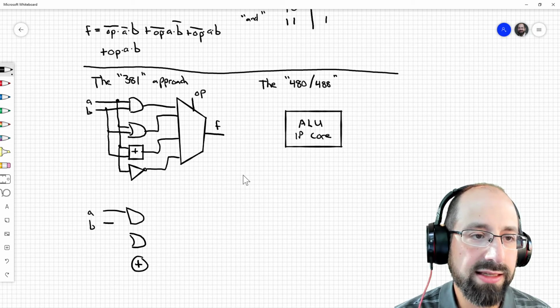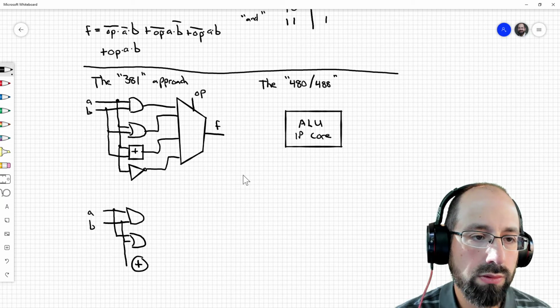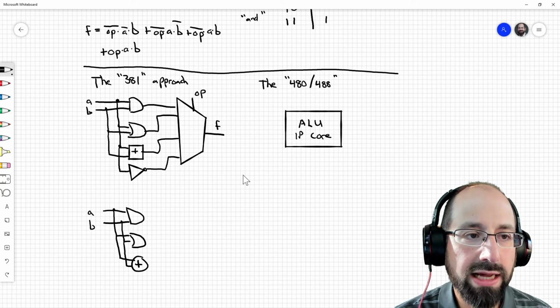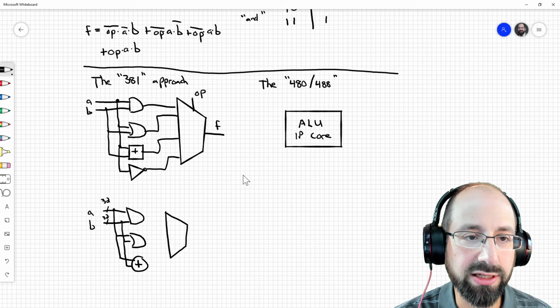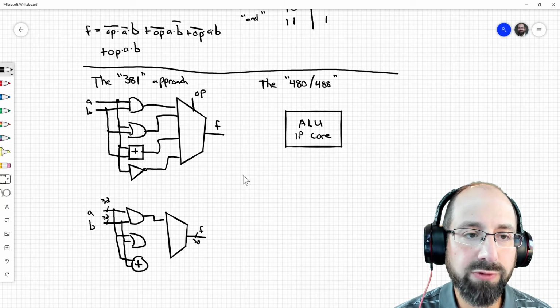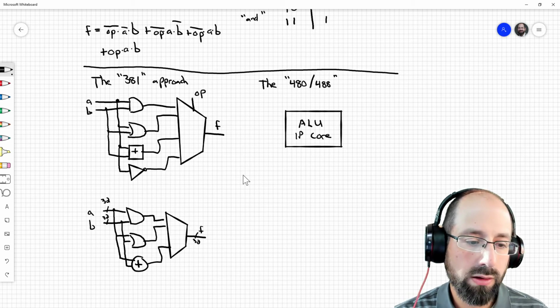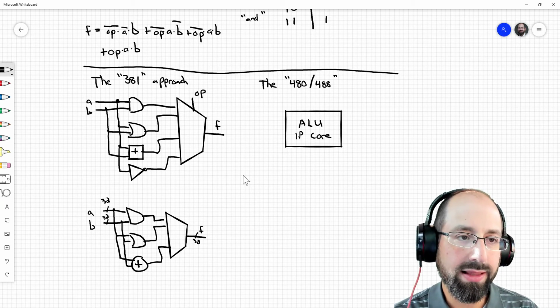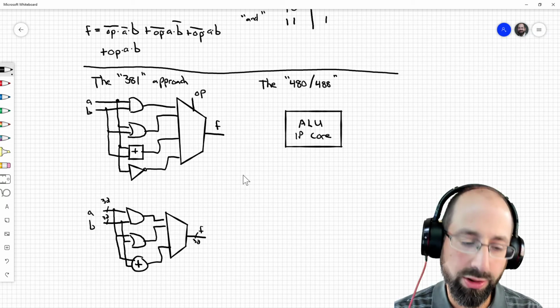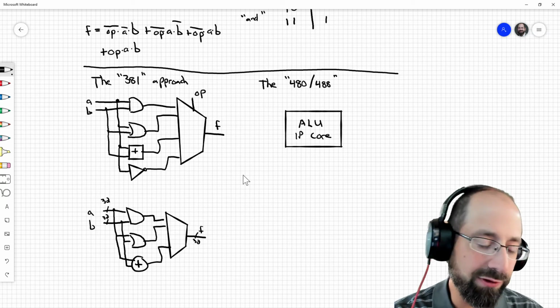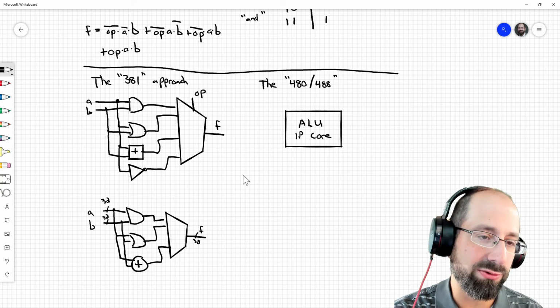this single bit ALU that we've created, why not just do this entire design, which we now know how to do? And if I had asked you to do it this way, this design should look extremely similar to the one above. Why build up from a 1-bit ALU at all? That would be a 32-bit AND gate, which we would know how to build, a 32-bit OR gate, and then either a data flow or other 32-bit adder, and then just mux those results.